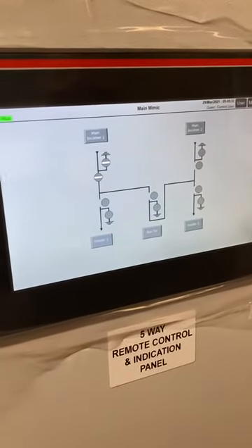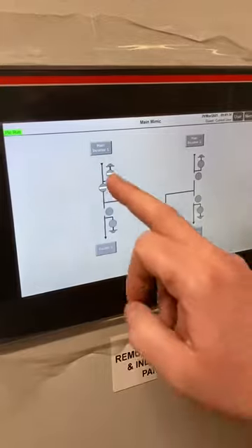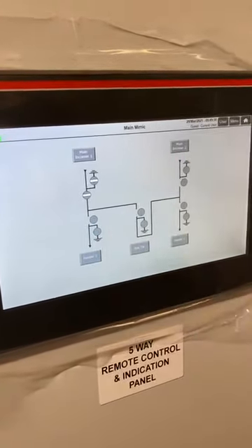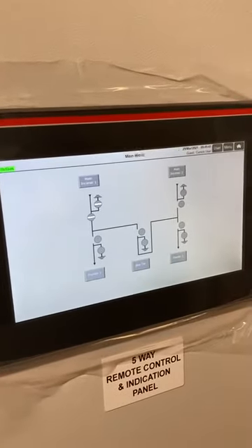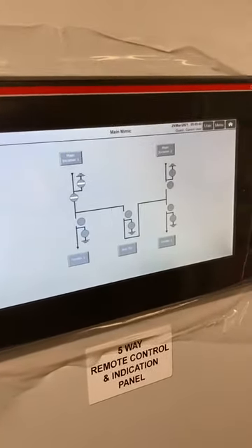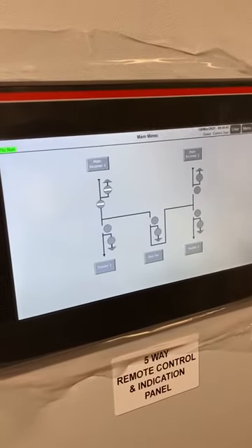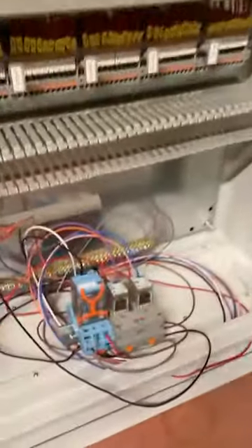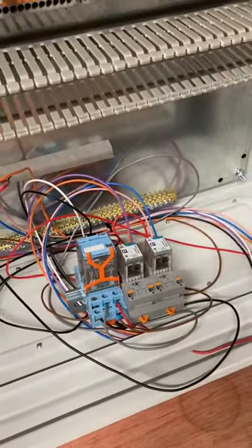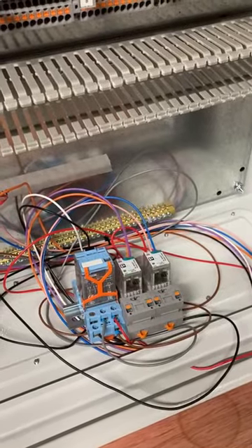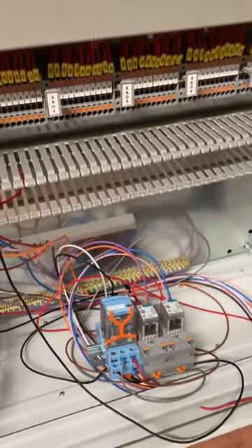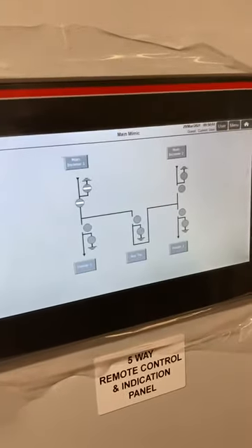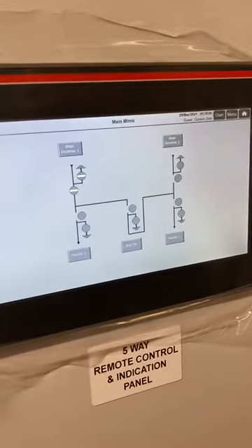So at the moment, if you try and press things there, it'll do nothing, no? Yeah. Okay. And the reason these are not lit up is because we're only testing one bay at the moment. One breaker being tested at the moment. And that's being set up here just to mimic the breaker, the withdrawn signal and the earth signal. Okay. So for instance, if you want to get in and change that breaker, what do?